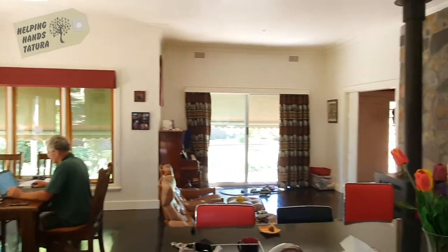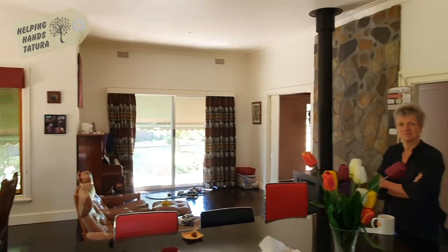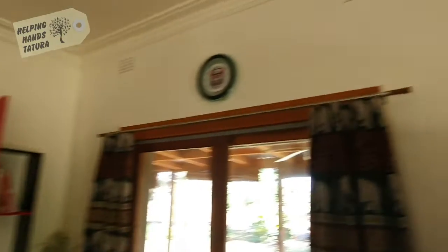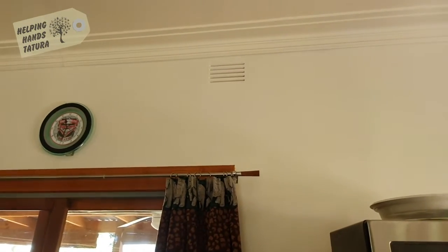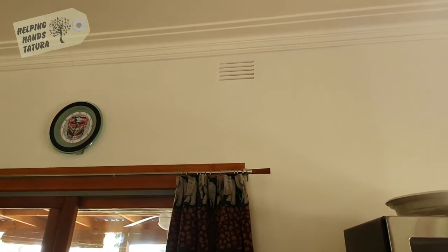Here we are in 2021 and we don't have gas lights, and this house does not have unflued gas heaters. So they are redundant and they are permanently leaking warm air in winter, and they're permanently allowing warm air to enter the house. So as far as improving the thermal performance of this house, low fruit, seal up the air vents. So how you fix them, there's a range of techniques.